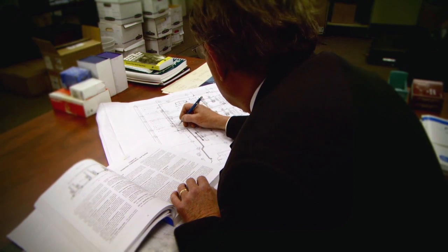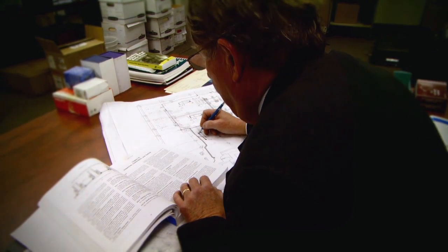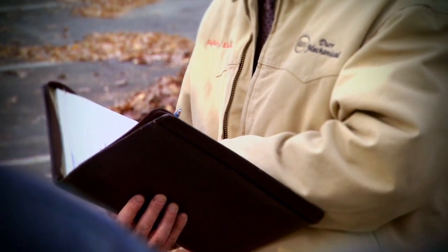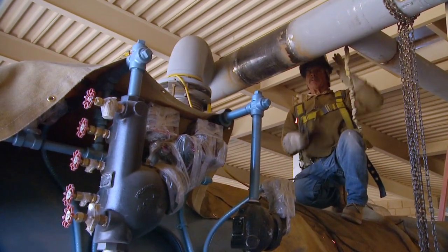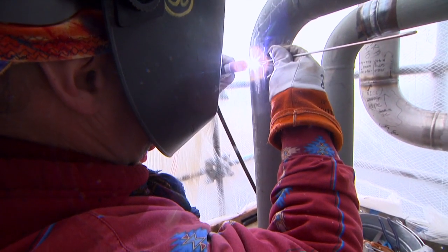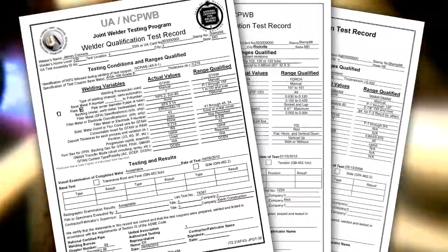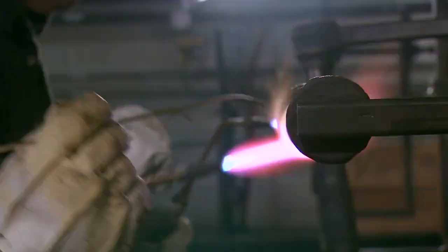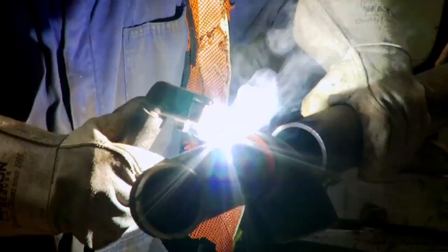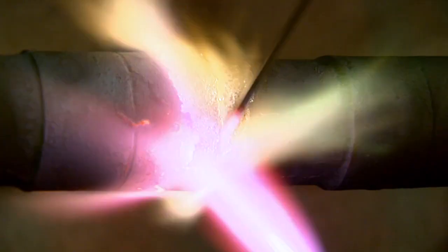While the engineer is responsible for material selection and design, the contractor is responsible for installing the piping following the specified B31 code section and the engineer's drawings and specifications. This includes being sure that the materials that the engineer specified are the materials that are installed, that the welders and brazers who will do the work have been properly qualified, and that those individuals are following properly written and qualified procedures when welding and brazing piping.